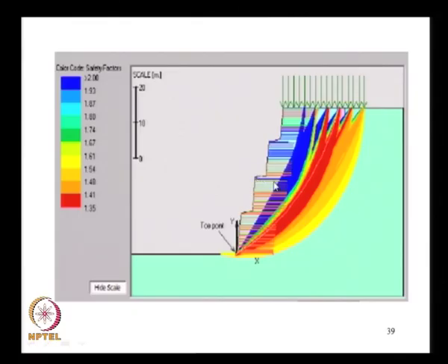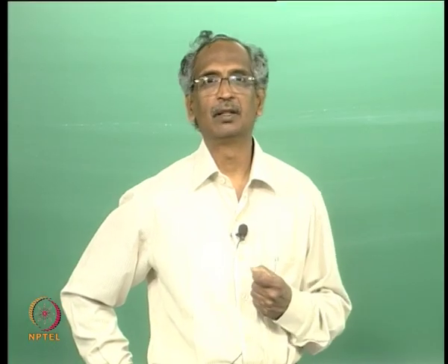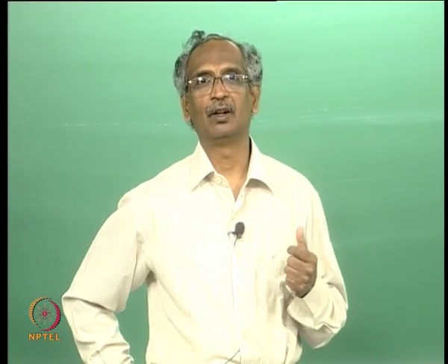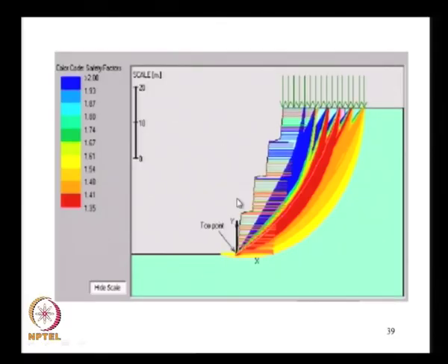And the design codes are a bit hazy about the design of tiered walls, and one suggestion made is although the entire system was designed as a retaining wall, we have to check for the global stability by taking different slip circles passing through both the reinforced fill and then the backfill, and make sure that there is adequate factor of safety under the worst case scenario, that is with seismic factors. And Vijayawada being in the zone 3 area, appropriate seismic factors were considered in the design.